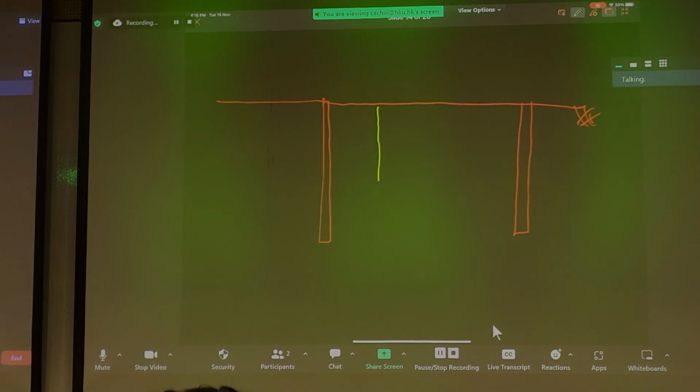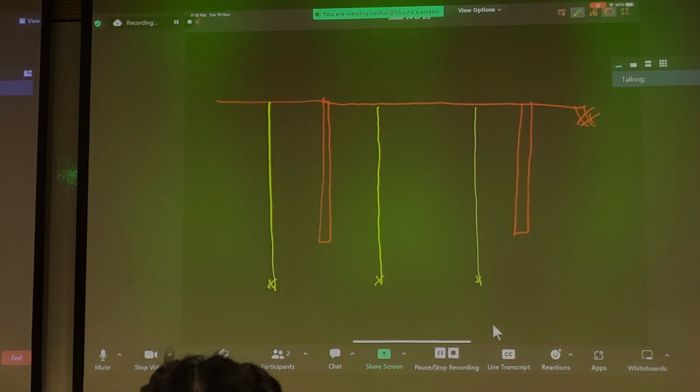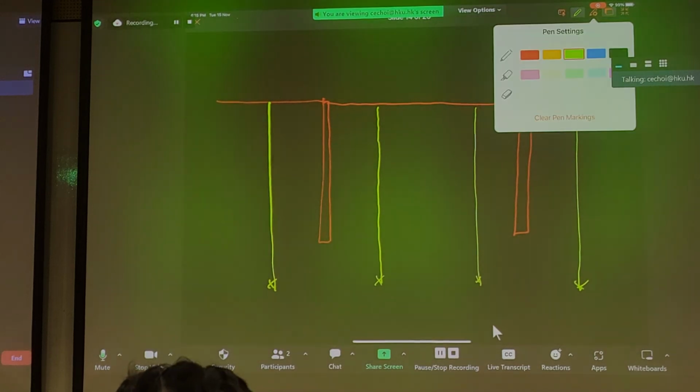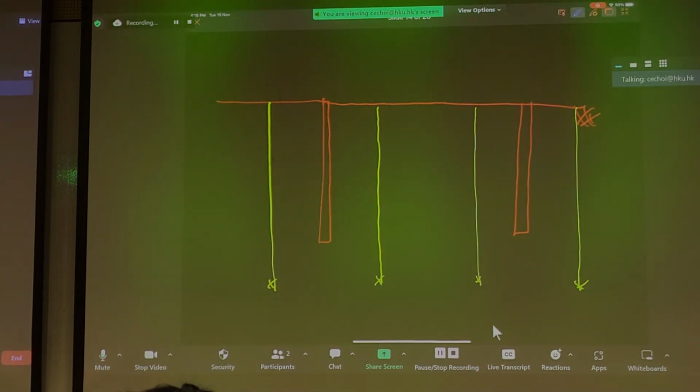We've seen some pumps here, sink a few pumps like this, and before we excavate, we can do a pumping test. And this is to check whether we can suppress our groundwater table. So this is a D-wall, or diaphragm wall, or sheet pile wall, whatever you like.